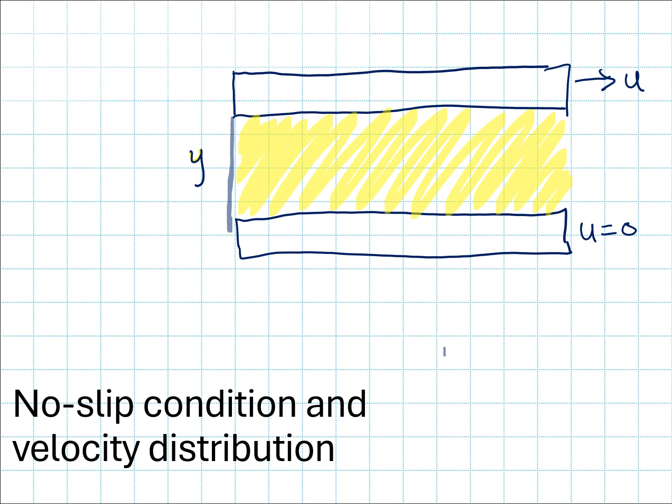So we learned in our last video that the fluid that is touching the bottom plate down here is moving at a velocity of 0, the same velocity as the bottom plate because of the no-slip condition. The first layer of molecules touching the bottom plate have to move at the same speed as the plate, and that solid plate is moving at 0, so the bottom layer is also moving at velocity 0, right? So this is my first layer of the fluid. My velocity is equal to the velocity of the plate, 0.